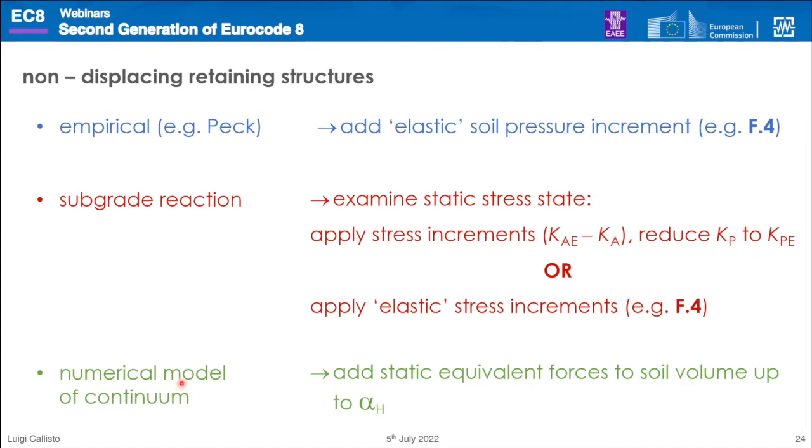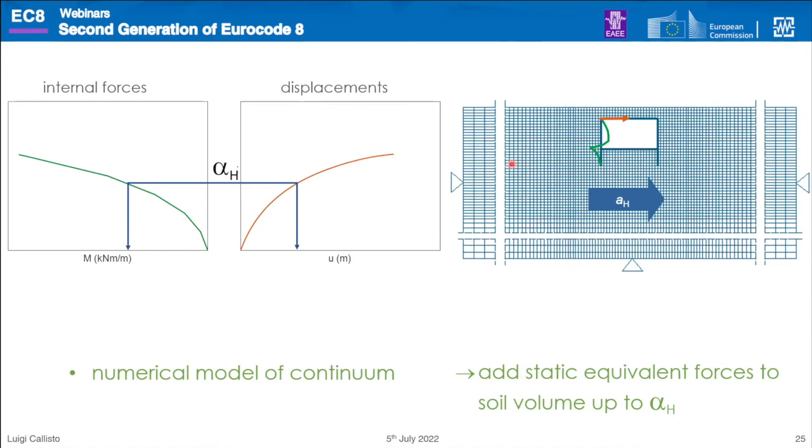If we have a numerical model of continuum that we have used to analyze our static conditions, then we may add the static equivalent inertial forces to the soil volume, meaning that we may just load this model with horizontal body forces proportional to the mass of the soil and the structure. And when we increase the acceleration, we will be calculating displacements and internal forces in all the points that we want. So when we have reached maximum acceleration, this analysis will give us the internal forces in the structural